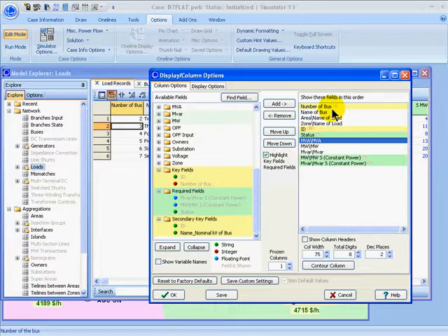In PowerWorld Simulator, we also provide an alternate or a secondary key for buses, which is the name and the nominal kV. And basically this allows you to use a heuristic for matching up data from one case to the next, or for one-line diagrams as well, which we had covered in the previous topic.